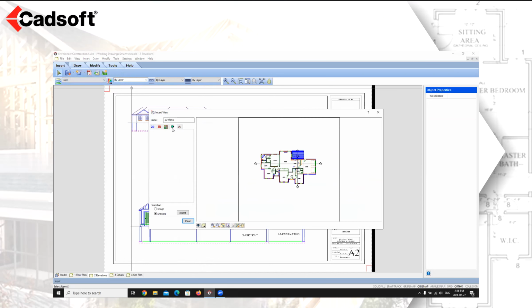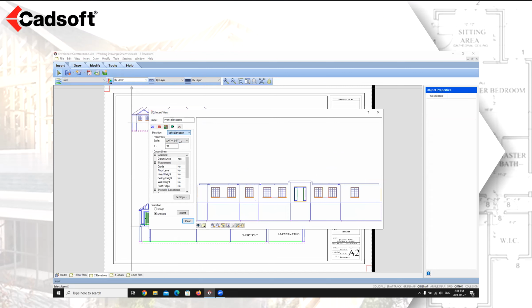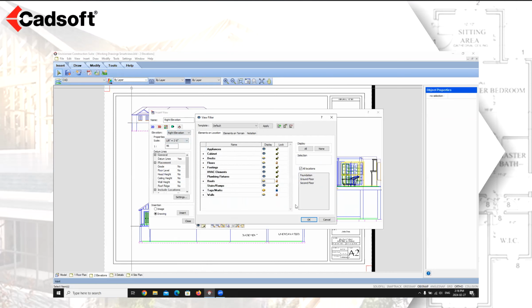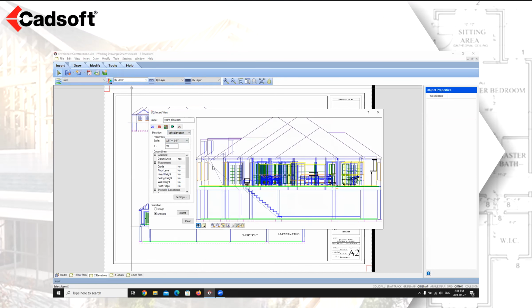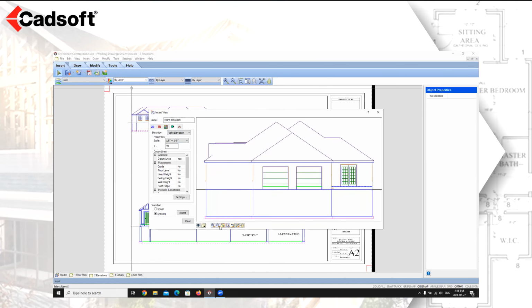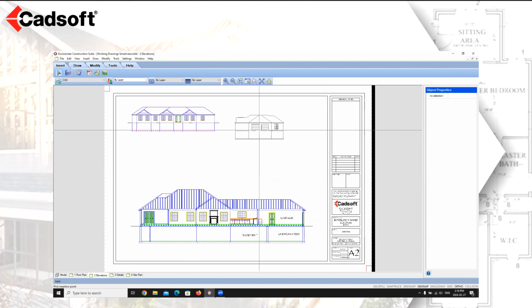at that same scale. So we're just going to go in and say right elevation. We're going to go up, we're going to say 1/8 of an inch scale. And we're going to make sure that we have everything turned on that we want. And we're going to zoom out a couple of clicks, like so. And then this should be hidden line. And we're going to say insert. And then attached to our cursor will be our next elevation.